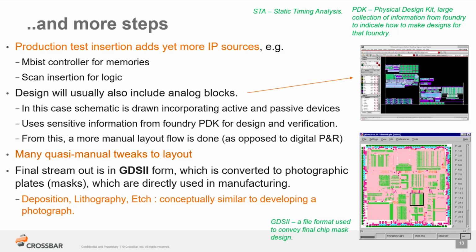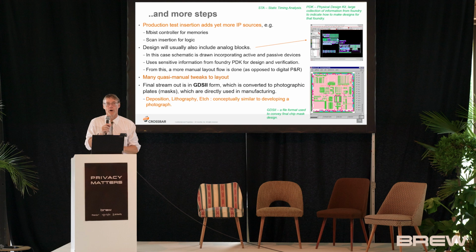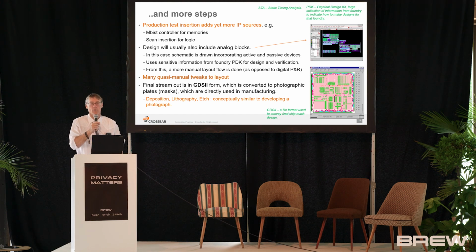After you've put this together and incorporated these other types of IP, there are test circuits also that have to be inserted. You don't want 100% of the chips to work on the wafer because that means you're not being aggressive enough in the manufacturing capability. You could shrink down and get more chips per wafer. So economically, the sweet spot is maybe 85% of the chips work because you're operating at the edge of the capability of the equipment.